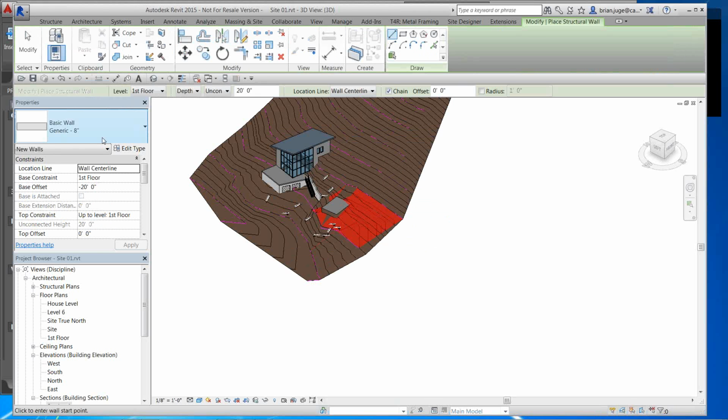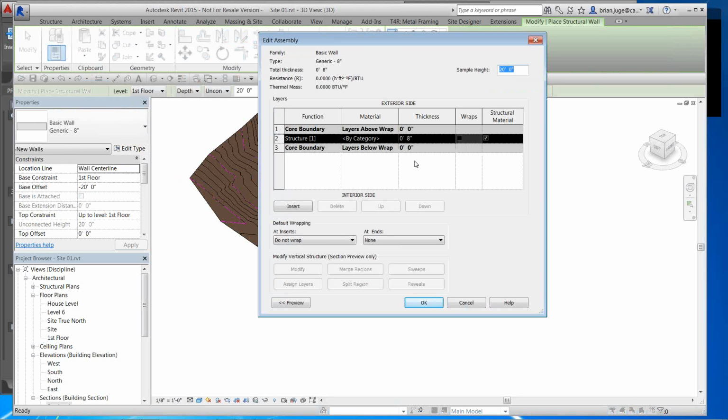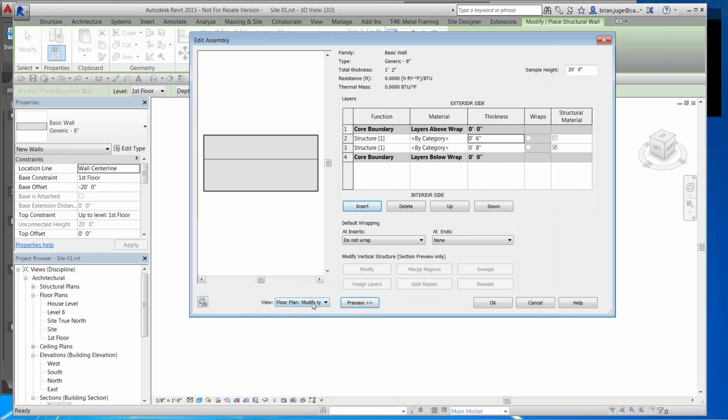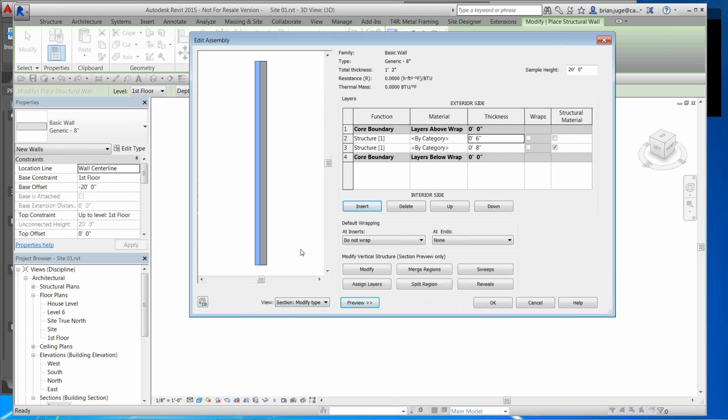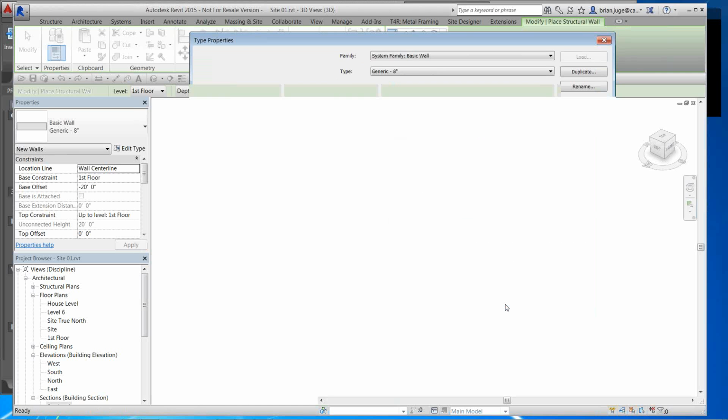see if I can create this wall. So my understanding, and Kyle, just make me understand, hopefully, I'm just going to put 2 layers in this wall. So I've got 8 inches and 6 inches for a structural wall. So we're not worried about what kind of material it is. I don't think that's going to come into play in here. So then I'm going to preview it. I'm going to put this in section. I'm going to reveal some secrets. Hey, you can actually unlock these layers. Come on, unlock it. There we go. So I can move this up and down.